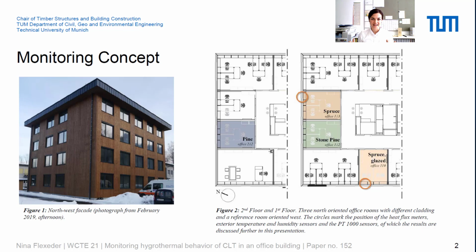However, today I would like to focus only on the spruce-clad offices, specifically their exterior walls facing west and facing north. Here we have placed temperature sensors, PT1000, as well as heat flux plates and sensors for measuring electrical resistance to gather information about the moisture content.